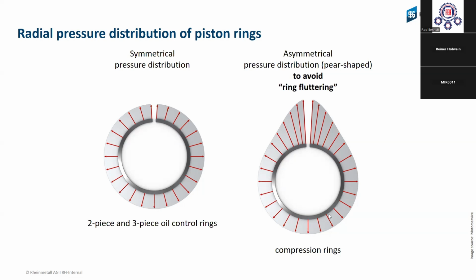And this is also when we don't have a line on the outside surface of the piston rings completely around, this will give me information that the piston ring's running-in is not finished. We must have a small line on the outside surface of the piston rings. They have contact on the piston ring, and then you see a small wear line. This is not very big, but shining more when you look at it with your eyes. And this gives me the information that the running-in effect was finished on this engine, or they must run